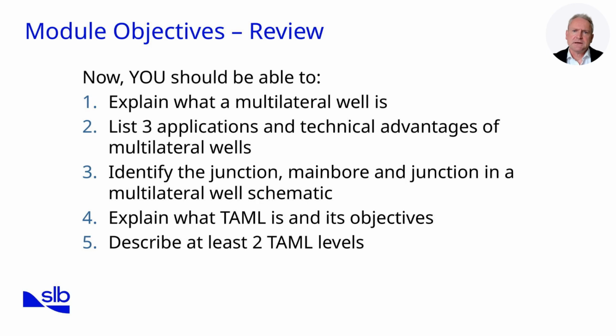Let's return to the objectives we outlined at the beginning. First, we set out to explain what a multilateral well is. We defined it as a main bore with multiple laterals branching from it, and reviewed diagrams to illustrate the concept. We then listed applications and advantages, covering both technical benefits such as increased reservoir exposure and reduced coning, and economic advantages such as fewer slots and reduced surface costs.